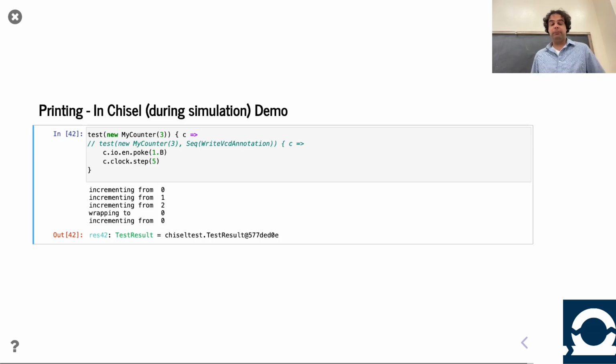So then what about waveforms? Let's do a waveform. We've got to do a slight tweak to the arguments to the simulation. For now, you can treat it as boilerplate, but this is turning on waveforms. For those unfamiliar with this term, VCD is short for value change dump. That is the most common format used for waveforms. There are other much better formats, but VCD is kind of the classic canonical one. So we have it in a lot of places.